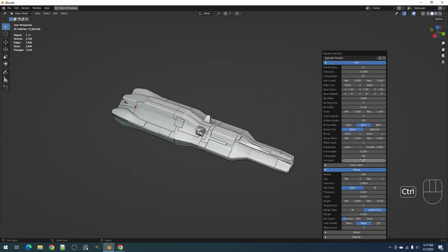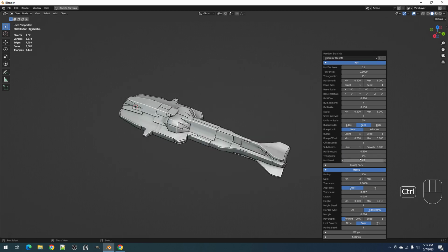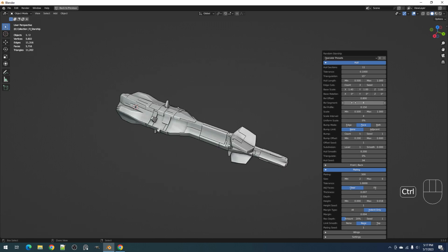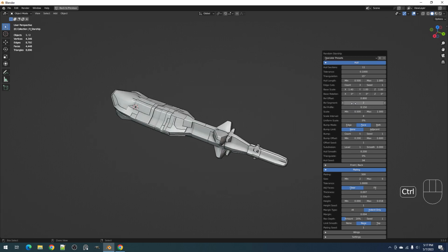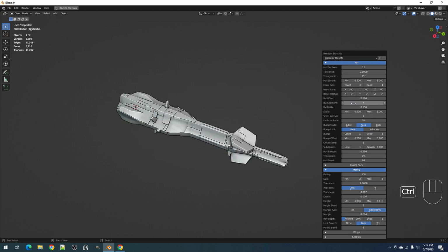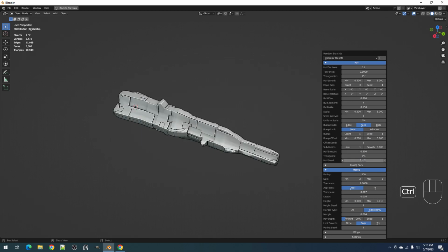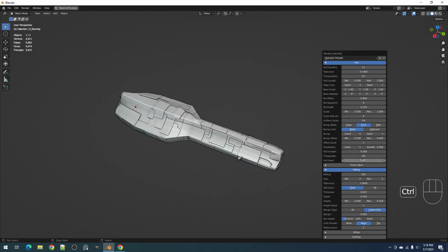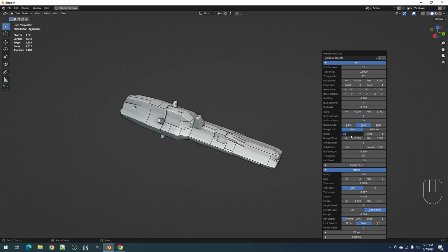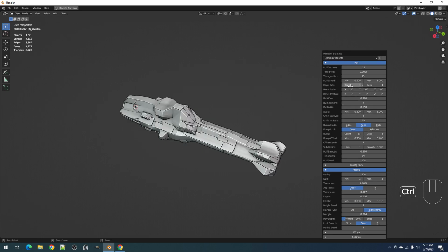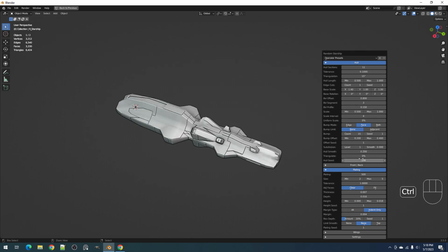Scale interval 3, increasing edge cuts to 3, bevel segment to 5. With the bevel segments, I only mostly work at 2 or 3. And as you can see, it's quite different from using higher bump values. Let's use 0.4 here and reduce the count to just 1 and this to 3.